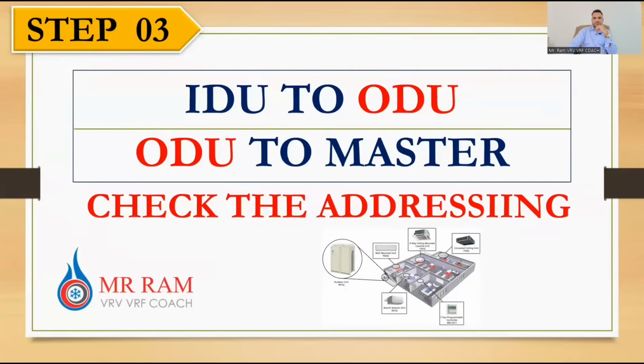After that, indoor to outdoor unit and outdoor to master unit, check the addressing. So, dear friends, basically for the indoor unit to outdoor unit communication, all the indoor units are connected in sequence, like one, two, and we give the numbers directly, manually or auto. Some series provide manual addressing, but some companies provide auto addressing. So first of all, we have to know whether the system has auto addressing or manual addressing, for the indoor and outdoor units, and also for the outdoor units.